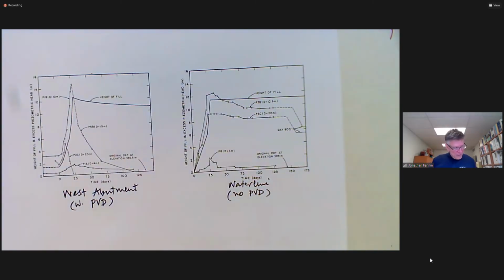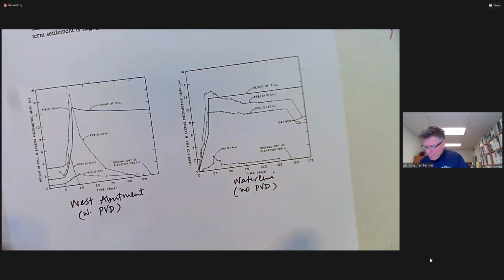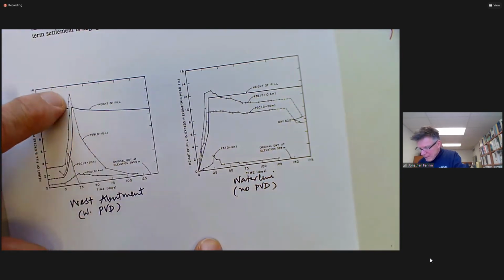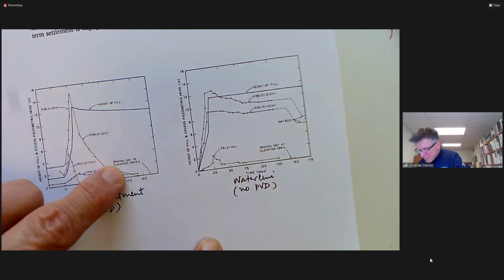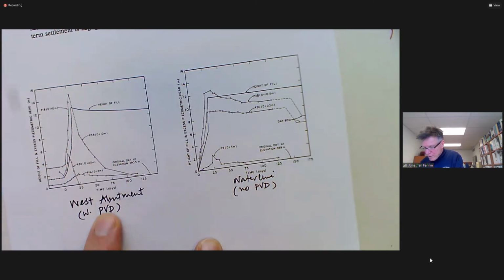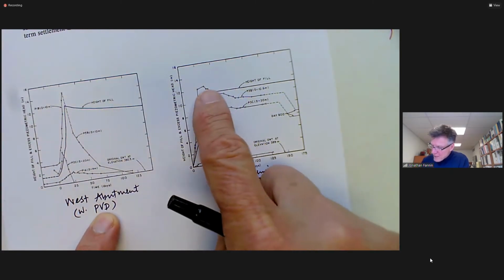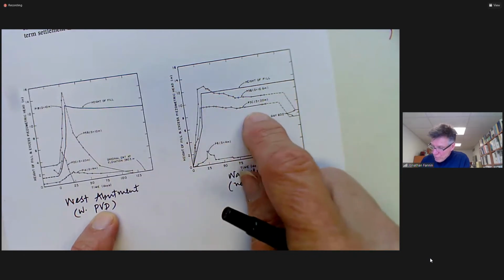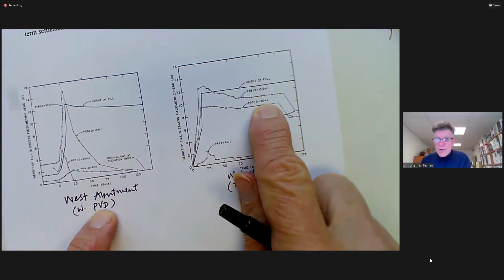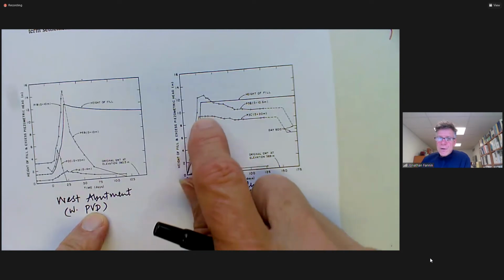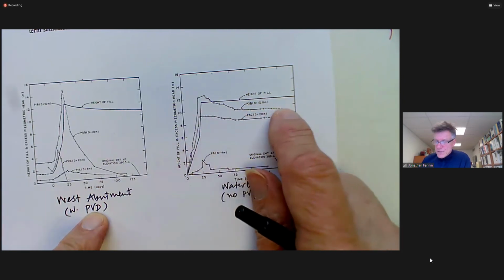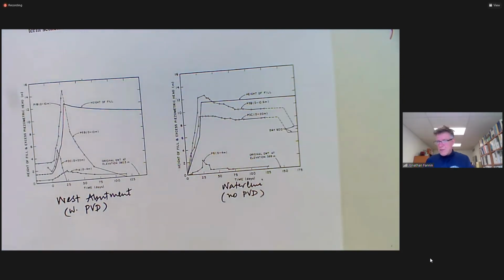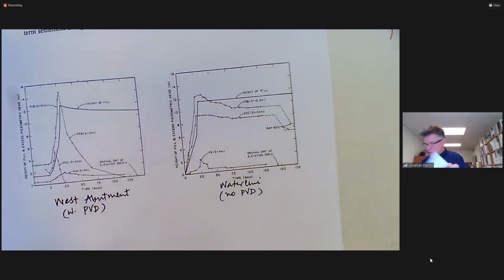And interestingly enough, we got very rapid dissipation of excess pore pressures with the prefabricated vertical drains, and little or no dissipation at depth, 10 meters and 20 meters, little or no dissipation of excess pore pressures with depth. And, you know, upon first inspection, you say, well, that's really weird.